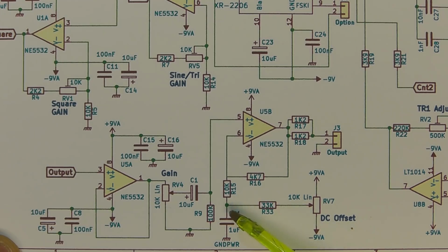As far as signal is concerned, that point is ground, but we can inject a voltage at that point. What I'm doing here is I've got a 10k linear potentiometer, where I've got plus 9 volts or plus 6 volts on one side and minus 9 or minus 6 on the other, so we can swing between the two, and we can apply that offset voltage to that point there, which will then effectively sit this output amplifier on that voltage and hopefully shift the output signal. So we'll give that a go and just see how that works.